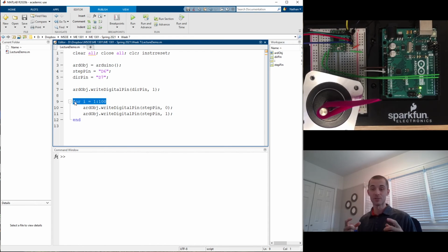The way that the drivers or the additional boards work with the hardware, and also the way that I program the Arduino to emulate the hardware, I forget how they're set up, but we have to actually configure the pins to be pulled up so that we can have usable logic on there. So we configure the pins to be in pull-up mode, which I should totally show you right now.